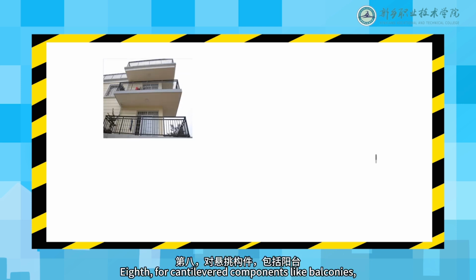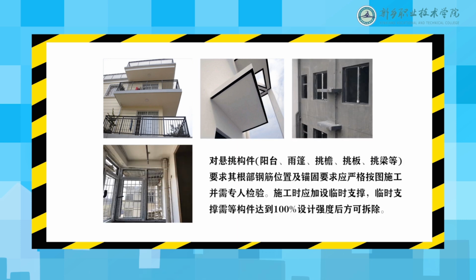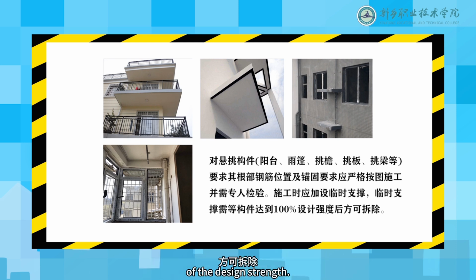Eighth, for cantilevered components like balconies, canopies, eaves, slabs, and cantilevered beams, the placement and anchorage of reinforcement at the root shall strictly comply with the drawings and be inspected by designated personnel. Temporary supports are required during construction and only removed after the member reaches 100% of the design strength.